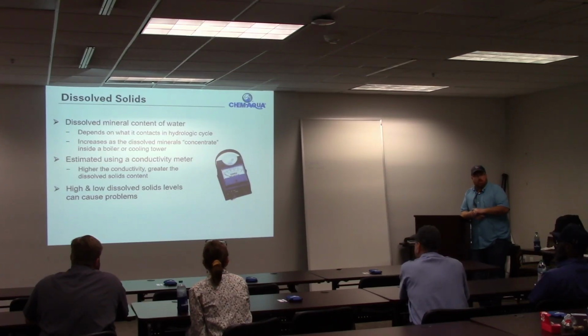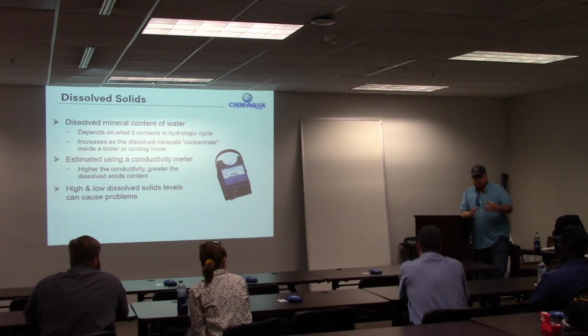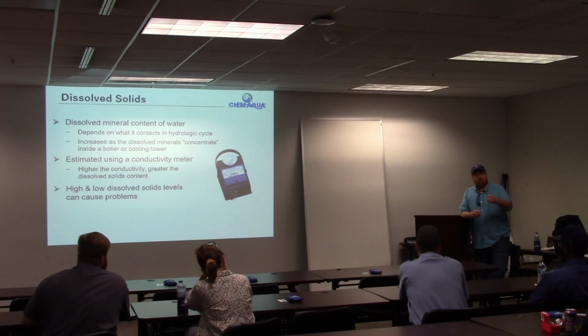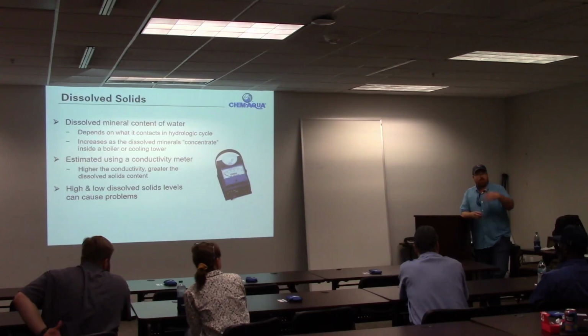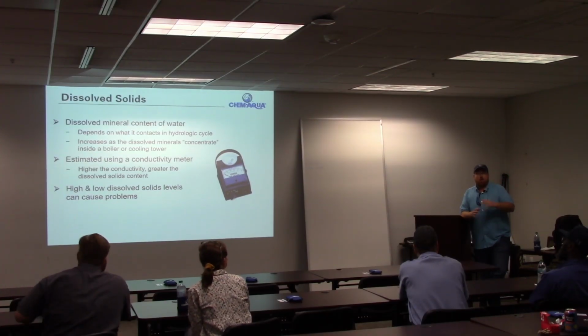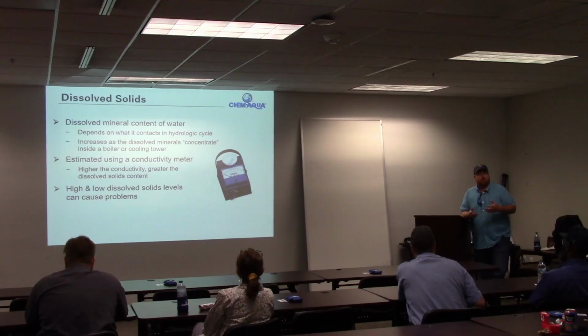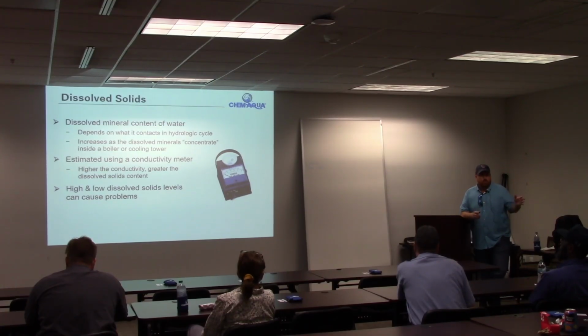Does sodium have a factor in that? Sodium, yes. Yeah. If you were to take a glass of water and dissolve salt in it, measure the conductivity, and then dissolve more salt in it, the conductivity is going to go up. So all dissolved solids are going to have an impact on conductivity, but there's only certain dissolved solids that are going to be limiting factors in terms of your water treatment. So sodium, for the most part, is not an issue. Sodium chloride is an issue because that's salt, right? But sodium itself is not a problem.